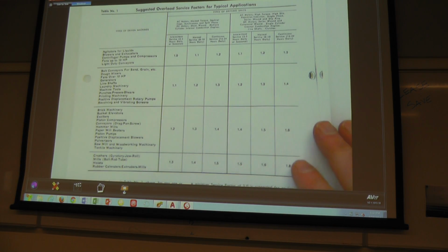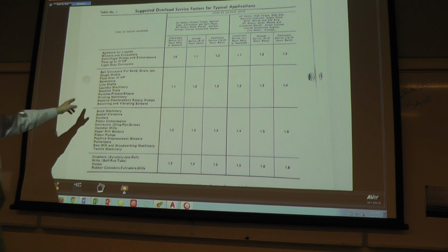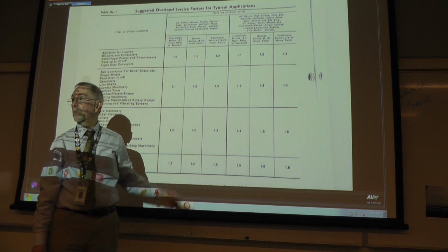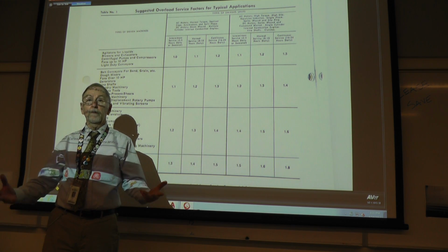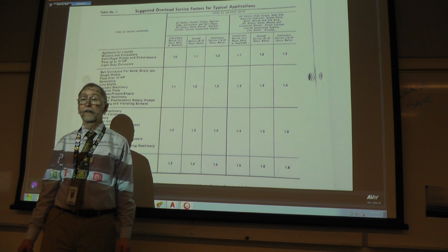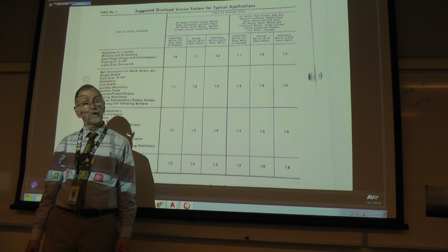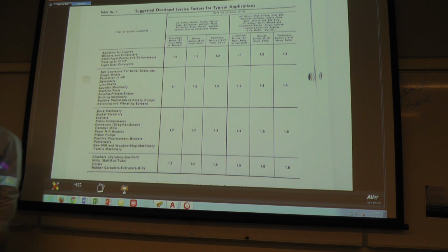This is another type of service factoring that is available. Well, dough mixers was kind of like that bakery equipment. So AC motors, normal torque, normal service, dough mixers, they're going to use a 1.2 service factor on that. So the information is out there, I just have to find it. If that's what I'm being asked to do, is to calculate sizes of chains, sprockets and things, which you might end up getting to do, having fun doing that.